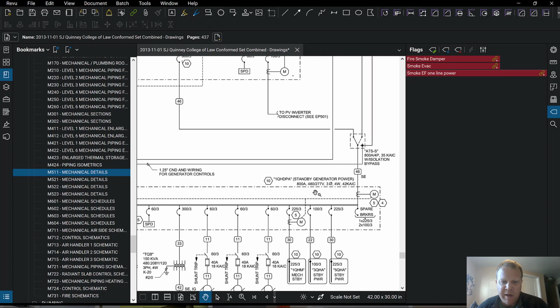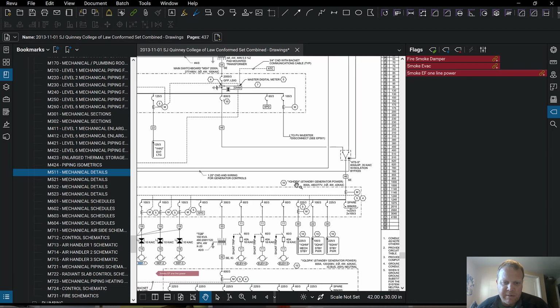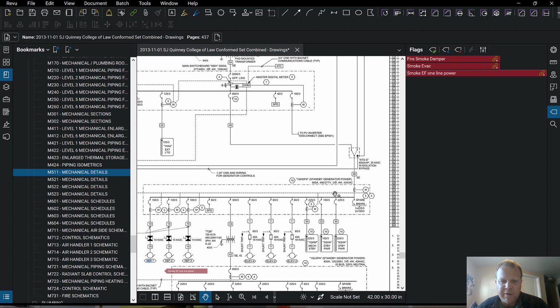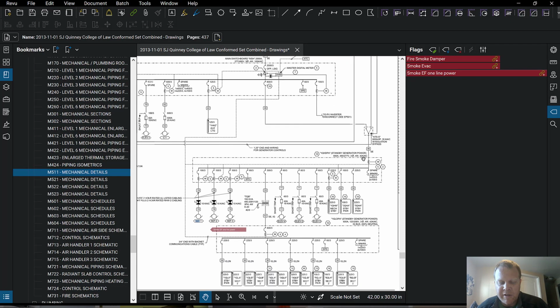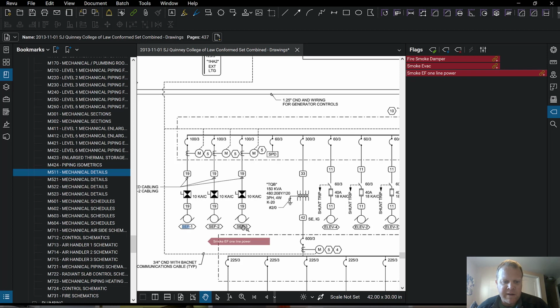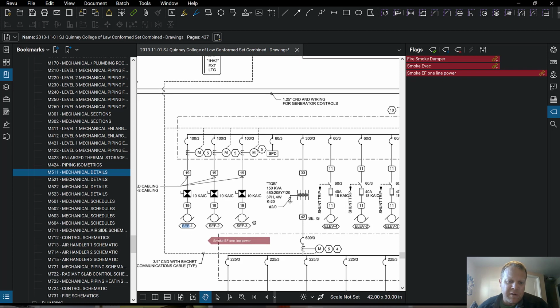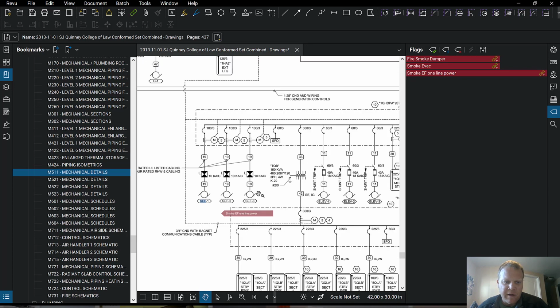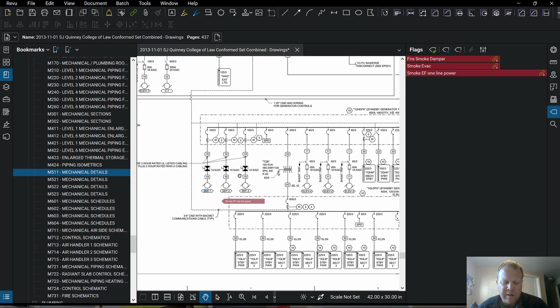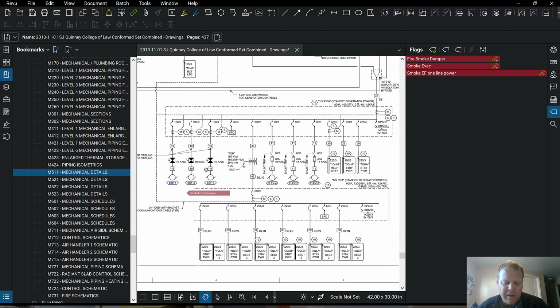IQHDPA is this panel right here. And whatever, I have no idea why they named it that, but this panel right here is being fed by two sources. One is the utility source, and then is also the standby generator. And check out what is on there. SEF, SEF, SEF. So all of the panel that feeds the exhaust fans, the smoke exhaust fans, they're not only powered by the main, they're also back on the generator power. When the generator kicks on, this will be on as well as the elevators